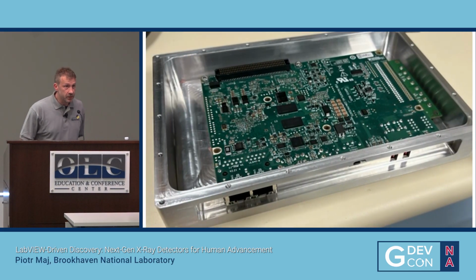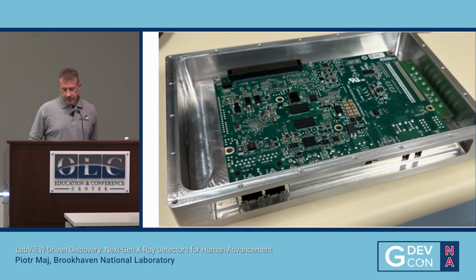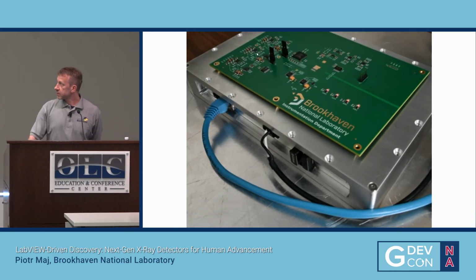And maybe I'll not talk too much, as the presentation is still long. We use passive cooling with an enclosure with very thick layers, because we want to completely clean our system from the noise from those PCBs. There are many DC-DC converters, and I just remind you that we measure single electrons of noise. That's very important.